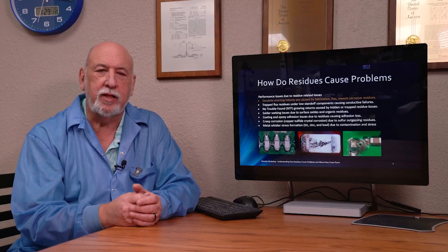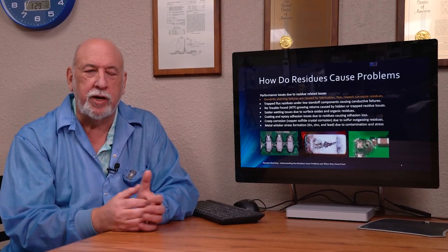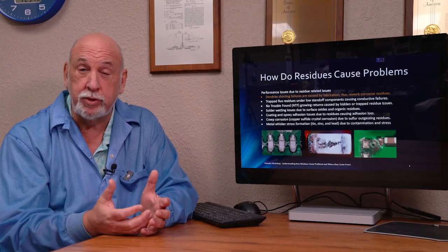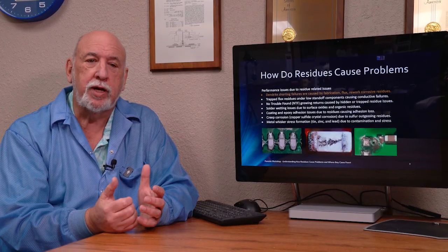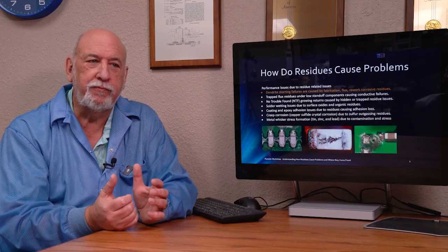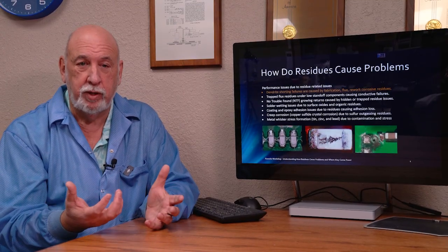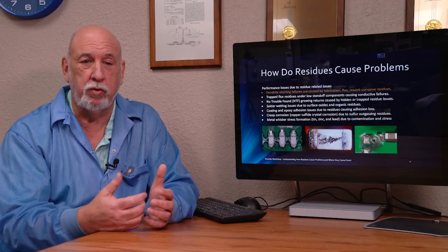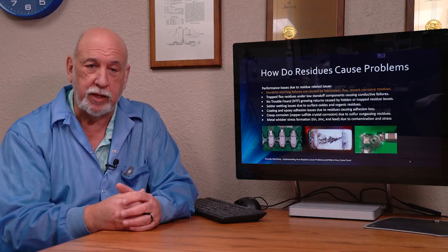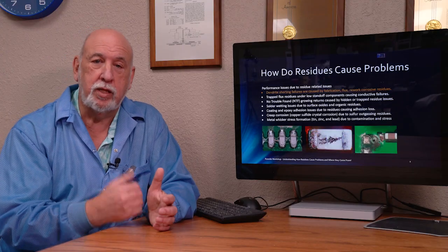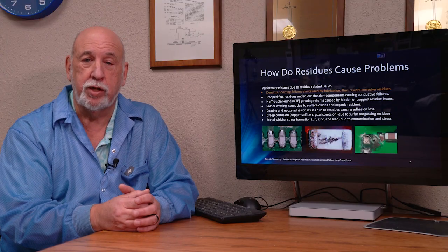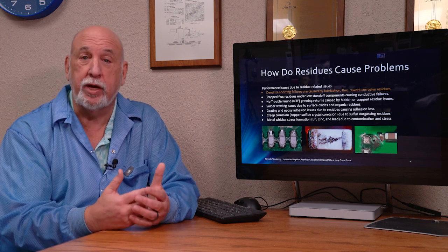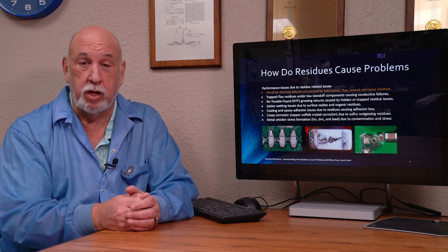The effect that they have is one of either creating a shorting event where there's intermittent performance issues, or where there's a fuse effect where it blows open. And then sometimes it can regrow, and as long as there's enough moisture and corrosive residue all in that same location, it can continue to create a shorting condition, to the point where in some cases it creates a thermal event, where actually the board catches on fire and starts to burn and causes more damage.